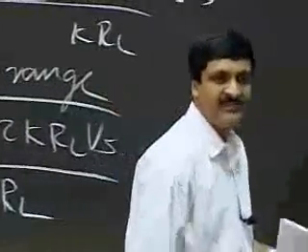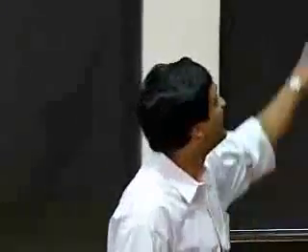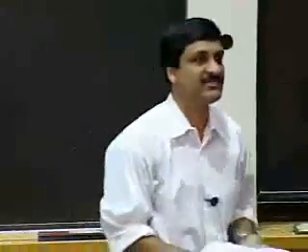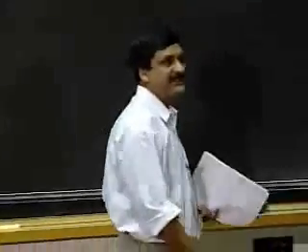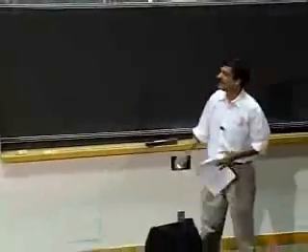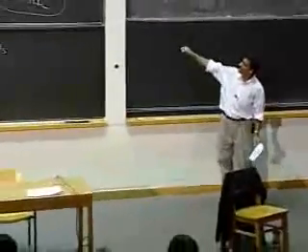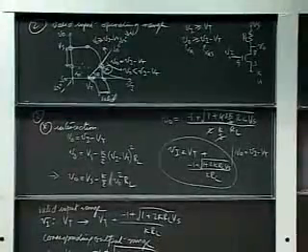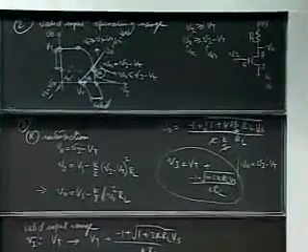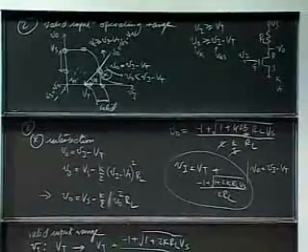It's pretty amazing as you get into this business and keep going down the path. It's amazing how some people really intuit or really get the load line thing, and others feel much more comfortable with the transfer function. So, pick whatever you want. Okay. So what we have so far is we've conducted a large signal analysis of a MOSFET amplifier. It's an analysis of a circuit, and we found two things. One is the transfer function under saturation operation, and we found the valid input operating ranges and the corresponding valid output operating ranges for the circuit.